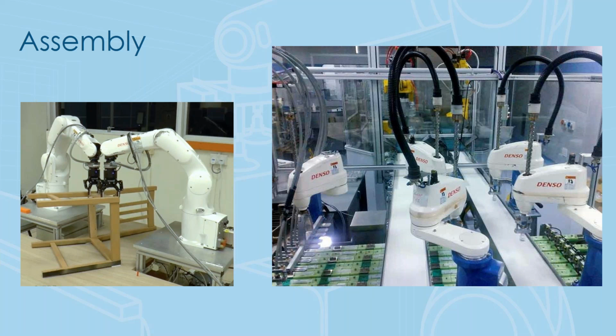We often see SCARA robots used for assembly if it's the right type of part. On the right, you'll see printed circuit boards, a surface mount application where these SCARA robots are acquiring parts off a moving conveyor and then mounting them on the surface of the printed circuit boards. This type of application, a pick and place type assembly application, and screw driving, as I mentioned earlier, are both excellent applications for SCARA robots just because of the nature of the geometry, where they can move quickly in X and Y, and they have that rigid vertical Z axis.